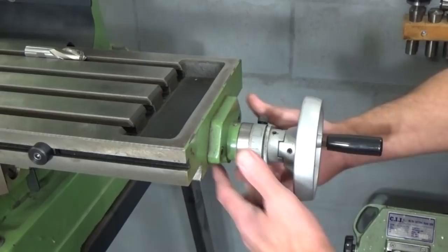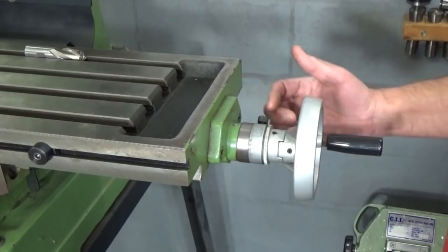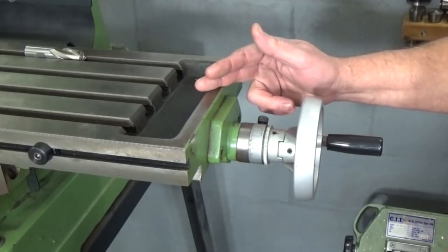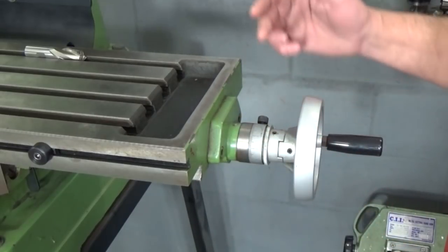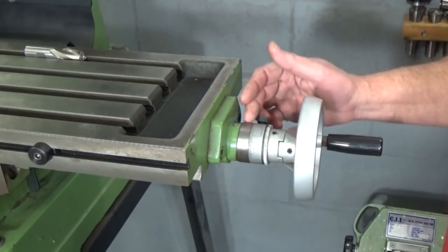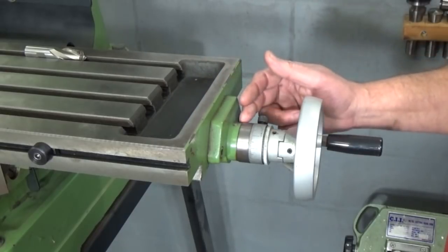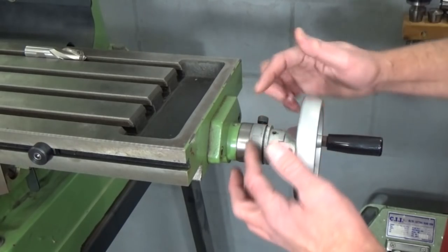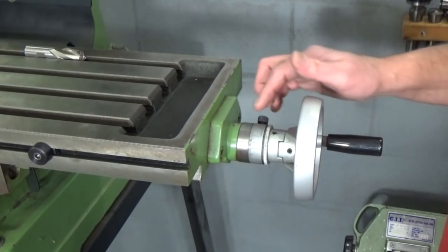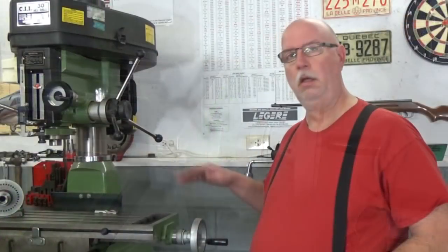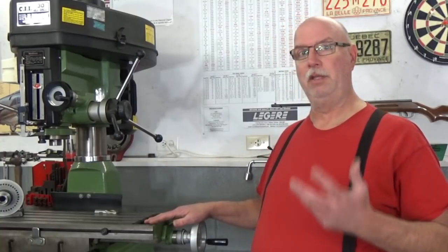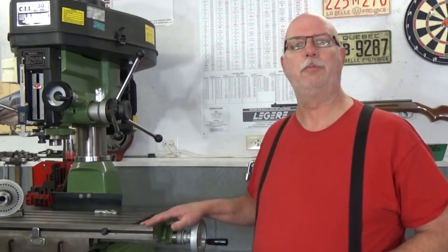This lead screw has a pitch of 0.1 because its pitch is 1 inch divided by the number of threads per inch. So 1 divided by 10, that means the pitch is 0.1. And I can see that clearly here. One full turn is 0.1. So the lead screw here is a 3/4 10 acme screw, and its pitch is 0.1.